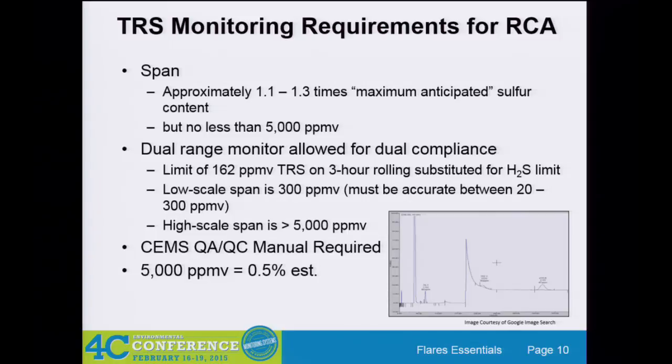So if you had a lot of, say, mercaptans in your liner, carbonyl sulfide or something like that, you've pushed your facility into a tighter threshold. So most people are not comfortable with going with that. They want to get that pure H2S number so they can get as high of a limit as they can get.